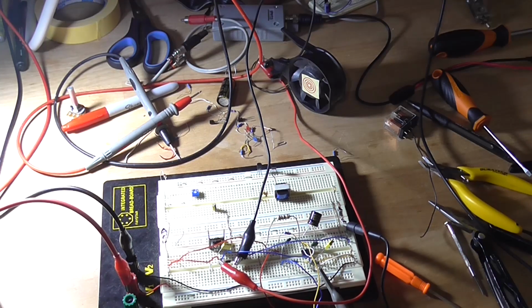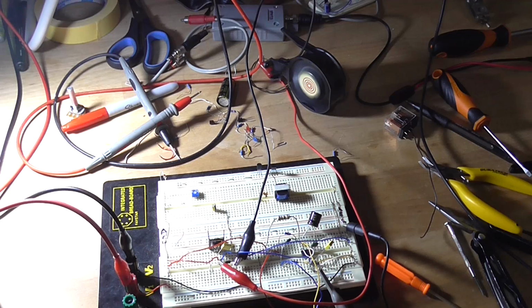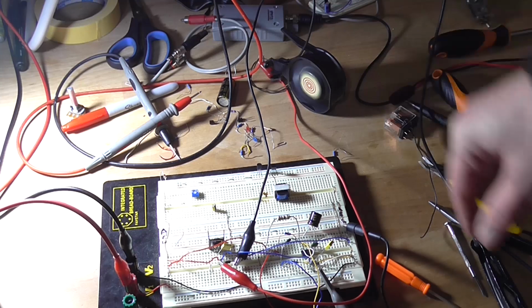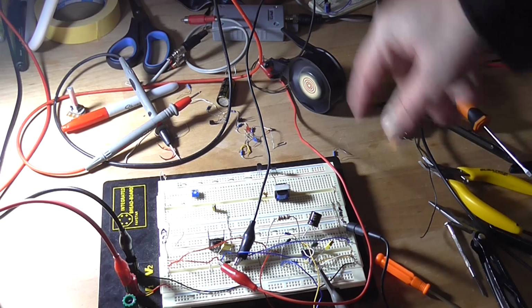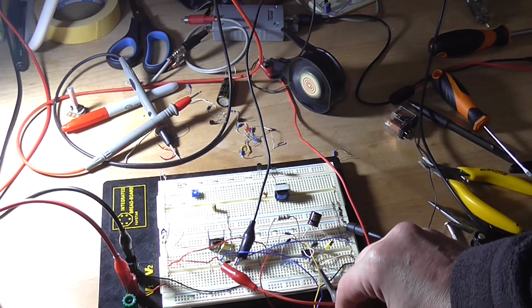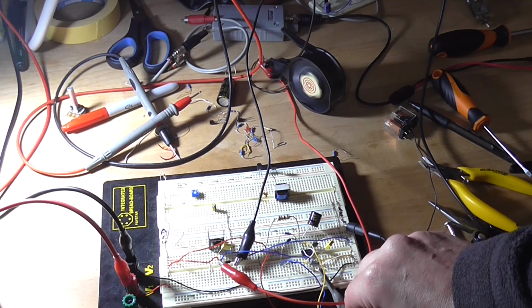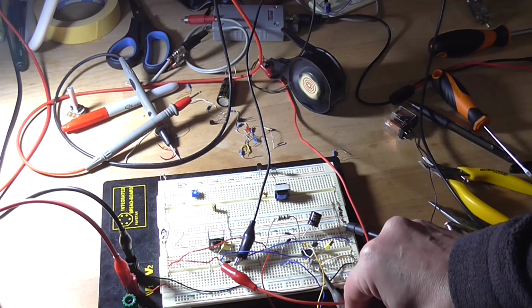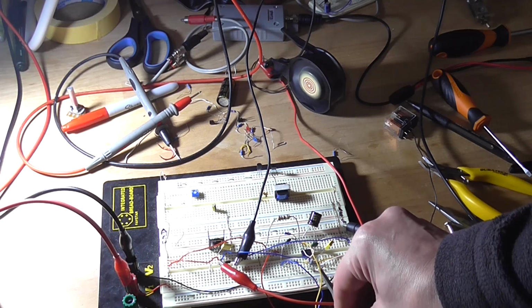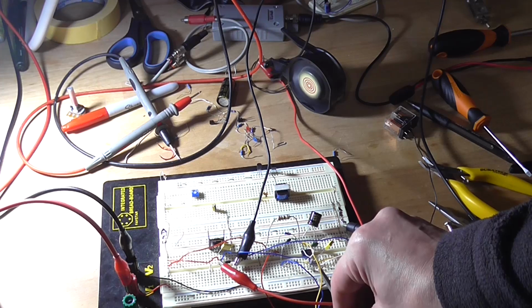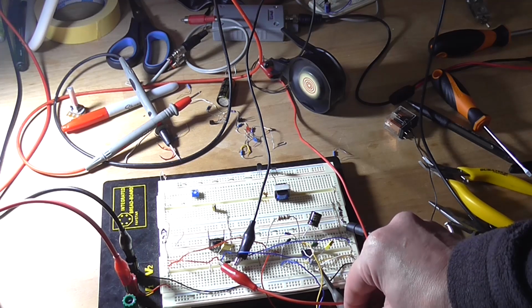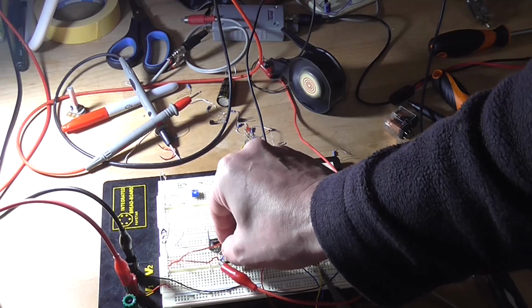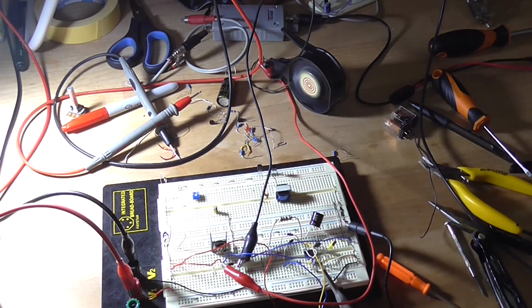So I've got the fan connected. Let's turn the supply on. Well, it works, but immediately we've got that noise of PWM on the fan motor. If I vary the pot, that's the slow speed, but I've obviously got the pot wired backwards. Yeah, so that 100 nanofarad capacitor, if I even pull it out of circuit completely, does absolutely nothing.